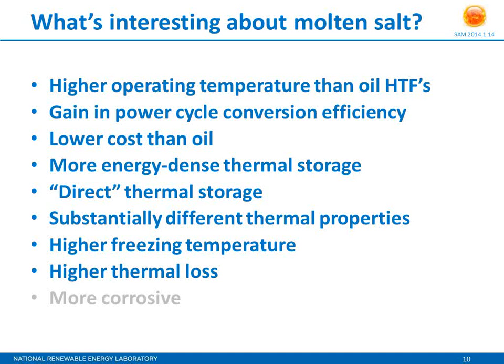So the heat transfer properties of molten salt are substantially different than oil. And so that introduces differences in the flow and in the pressure drop across the field, in the specific heat capacity. All those pieces are things we have to pay attention to as we're setting up the field.